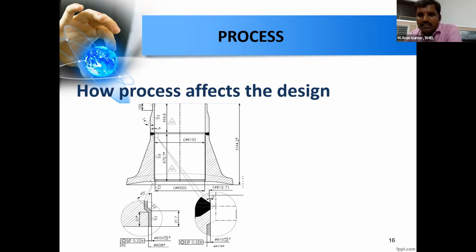There, the thickness is getting reduced, sir. If the thickness of cladding is getting reduced, what happens? This we have not foreseen during our design process. When the actual welding in shop has happened, they have removed the PT indication. Now the thickness of this cladding has been reduced to 3.5 mm, for example.